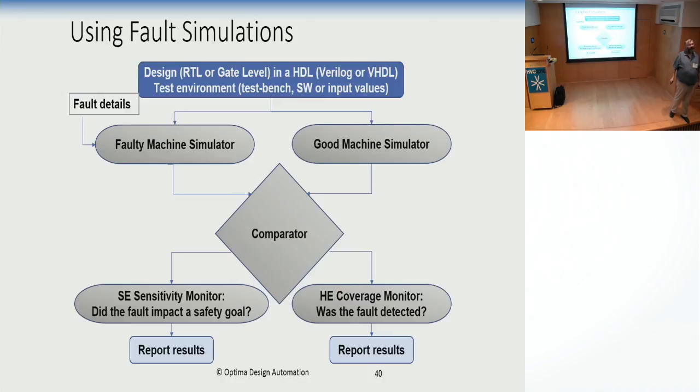So the fault model that we are using for soft errors is a bit flip at some point in time that can be later overwritten like any other value. And for hard errors, the most common model is stuck-at, but there are a few related failure models for hard errors that can also be understood.